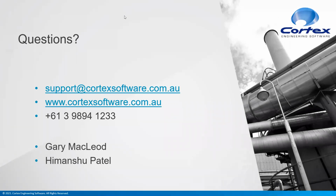So you got a couple of questions here, Gary. If you can see your Q&A box, otherwise I can read them out. So I got one from one of the attendees. Does the Extreme cover many different types of control valve trims, such as multi-drag, multi-hole, multi-path type, where kinetic energy across the trim is dissipated, producing lower thrust force?